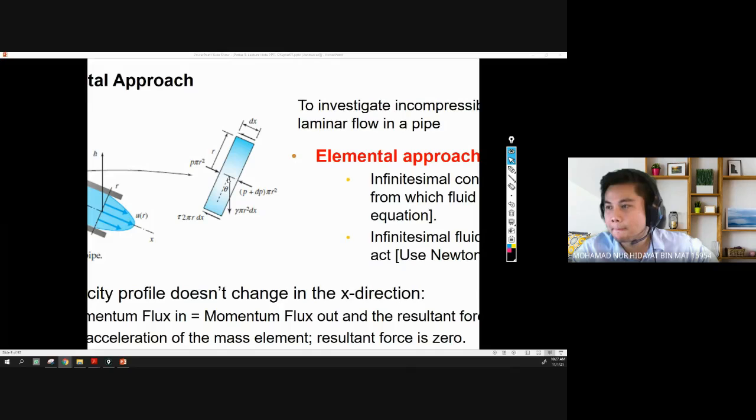So what happened to the body force? We have the force, which is rho g V. This is the body force. Remember our buoyancy effect. This term is rho times area times height. Let me simplify this: rho V. We have the body force F body equal to gamma V, rho g V.